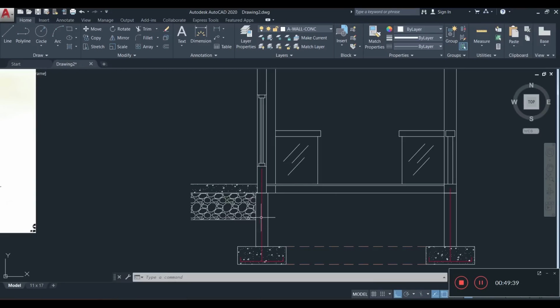Now there are standards in relation to it. You'll normally have the bearers running the shorter distance and the joists running the longer distance. So bearers are on top of joists. What is going to happen is you're going to have some running horizontally like this, and some running the other direction, so you'll just see the ends of them. Both of them we can have the same size. So I'm going to draw a rectangle so you can see what's going on here.